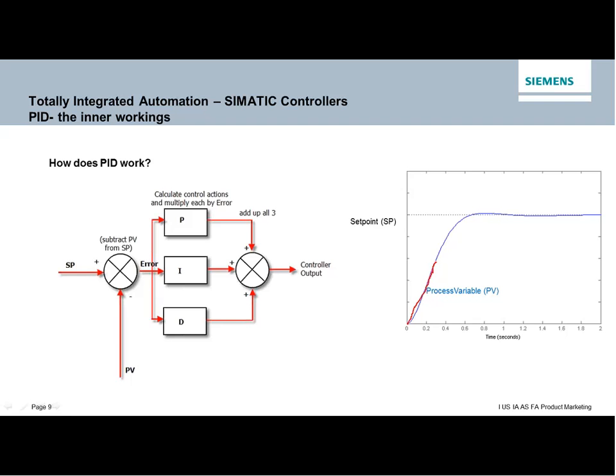So eventually what happens is we level out at an area where we have an offset from our set point, because we've lowered the error to the point where the P can't get the rest of it. And that's where we bring integral in. Integral looks at the amount of error over time. What it does is slice up the error in time increments and add that to the output. So if we have an error in here, and excuse me, I'm trying to write with a mouse here, every time increment it's going to add that to the output.